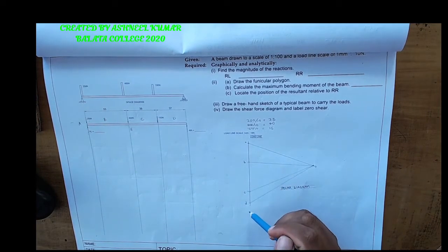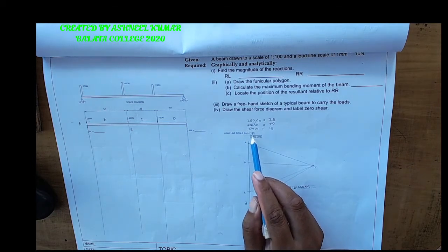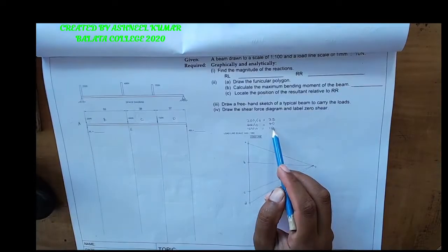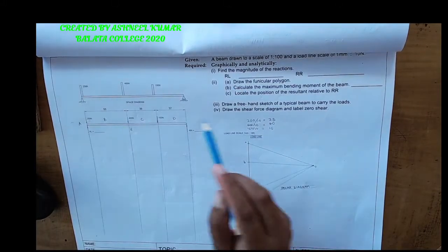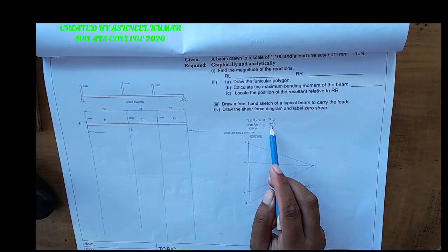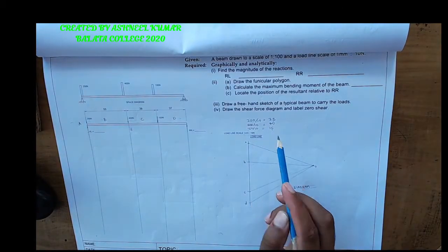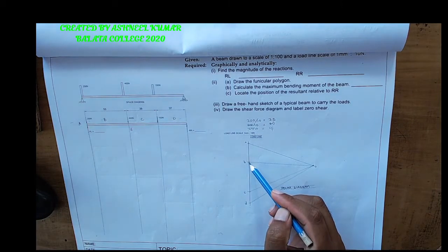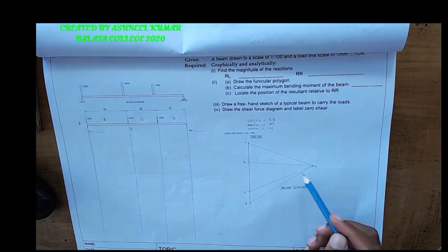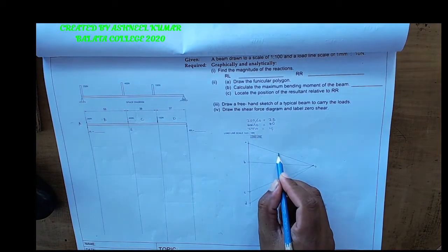After that, you're going to complete the load line, and to do that, you have to know how to use the scale. The scale says 1 mm is 10 newtons. This means all the forces here, I have to divide by 10. So A to B is 250, 250 divided by 10 is 25, B to C 400 divided by 10 is 40, C to D 150 divided by 10 is 15. So I'll measure A to B, that's 25, B to C 40, and C to D 15. Then I'll join all the points to O. That diagram will be a polar diagram. And also draw the arrows here.